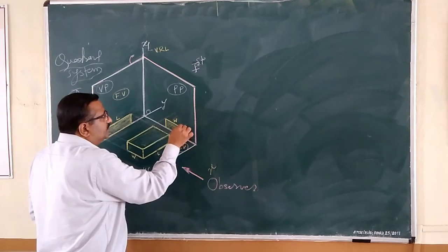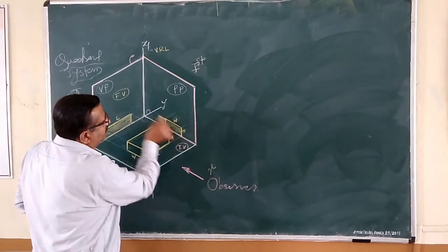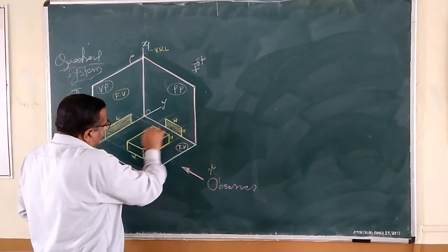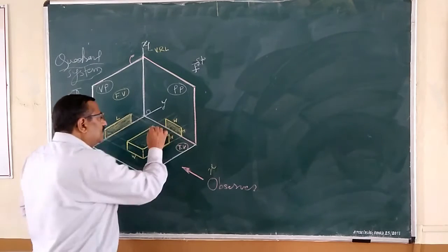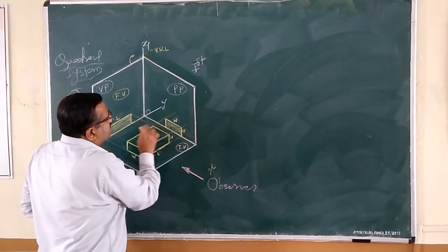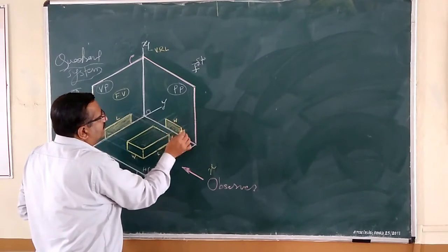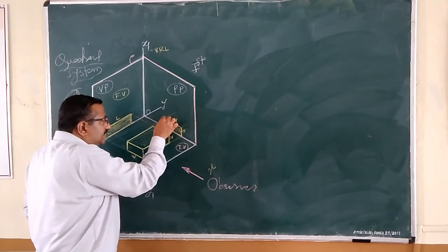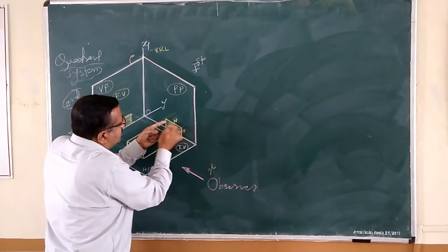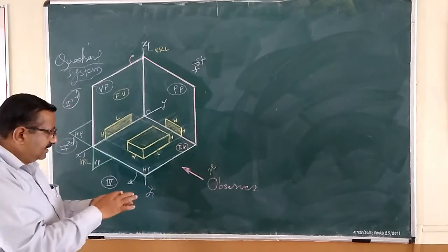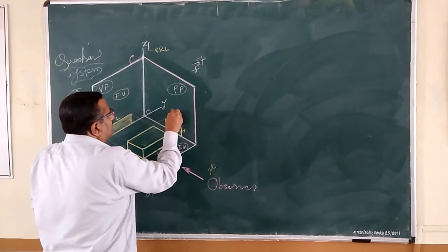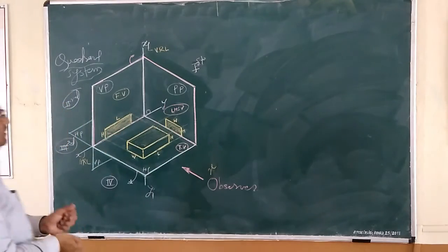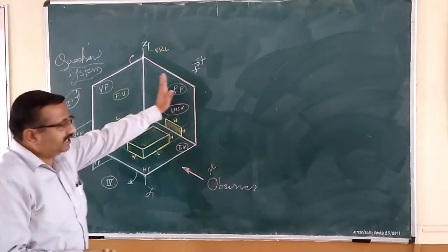Blindly through this point, parallel to left 30 I have drawn one projector, and this top line, left extreme, right 30 line of this object I have extended, it has cut this projector or construction line here, and from here I have taken its vertical intercept. This shape and size is yielding us the desired left hand side image which has been created on the profile plane.